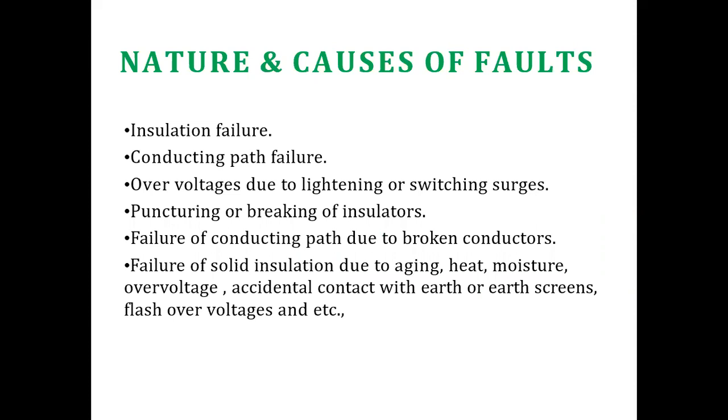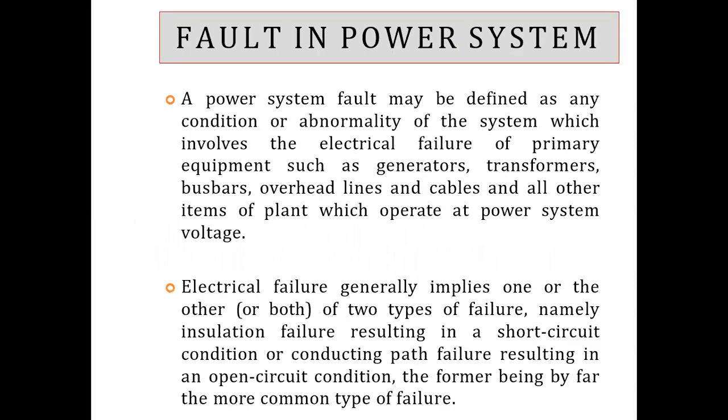The first cause is insulation failure, the second is conducting path failure, the third is overvoltages due to lightning or switching surges, the fourth is puncturing or breaking of insulator, and the fifth is failure of conducting path due to broken conductors. Then there is failure of solid insulation due to aging, heat, moisture, overvoltage, accidental contact with earth or earth screen, flashover voltages, etc. These are the causes and nature of faults.